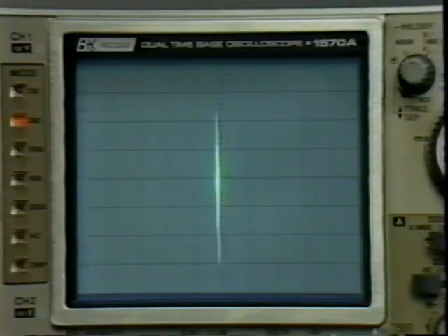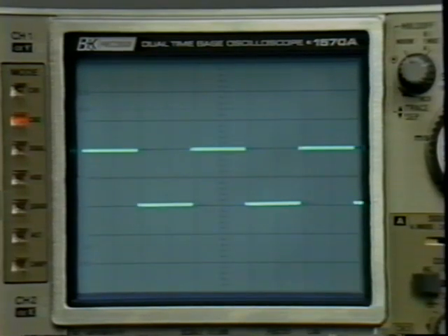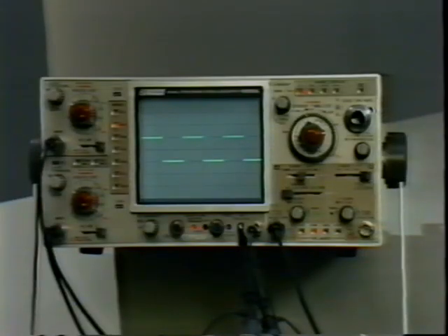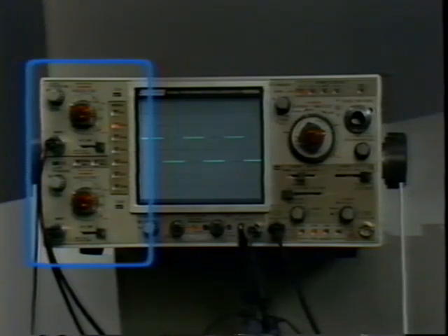The vertical section of the oscilloscope moves the beam up and down on the face of the screen to represent voltage, and the horizontal section of the scope moves the beam across the screen to represent time. Let's trace a signal through the scope to see how this happens. Many scopes have 2 voltage input channels that operate in an identical manner. The input channels of your scope, usually labeled A and B, or 1 and 2, are connected to the vertical driver, which moves the beam up and down.